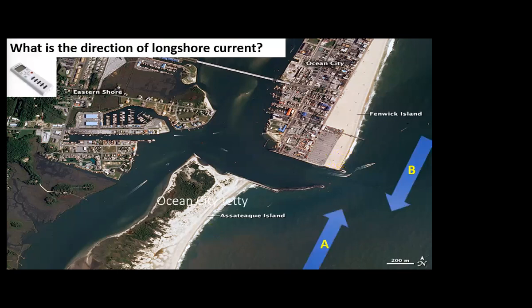Okay. So now which direction is this longshore current? Yeah, B. What makes you say that? Just because you can see... That's exactly right. So we get more deposition from where the longshore current is coming from. So always keep that in mind.